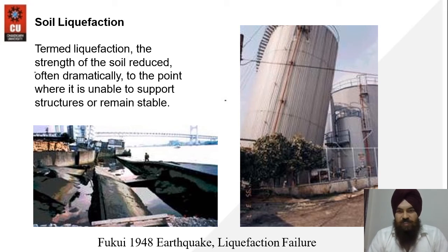This is the picture in which the structure has been designed properly. This superstructure has been designed properly to withstand the load, but the soil beneath the structure has shown failure through liquefaction during the earthquake. That soil has shown a reduction in strength for a small period of time during the earthquake.